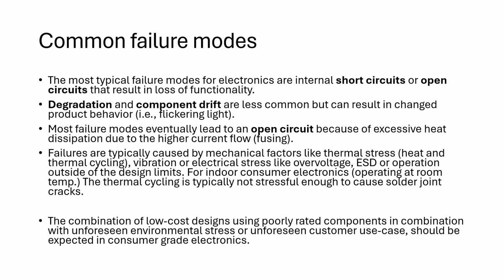A lot of these failures come from mechanical factors like thermal stress, heat, or thermal cycling. We could see vibration, not so much in consumer electronics though. And for the indoor consumer, the thermal cycling might not be the most stressful factor because we typically thermally cycle between room temperature and maybe 50-60 C. So here it might just be the heat.